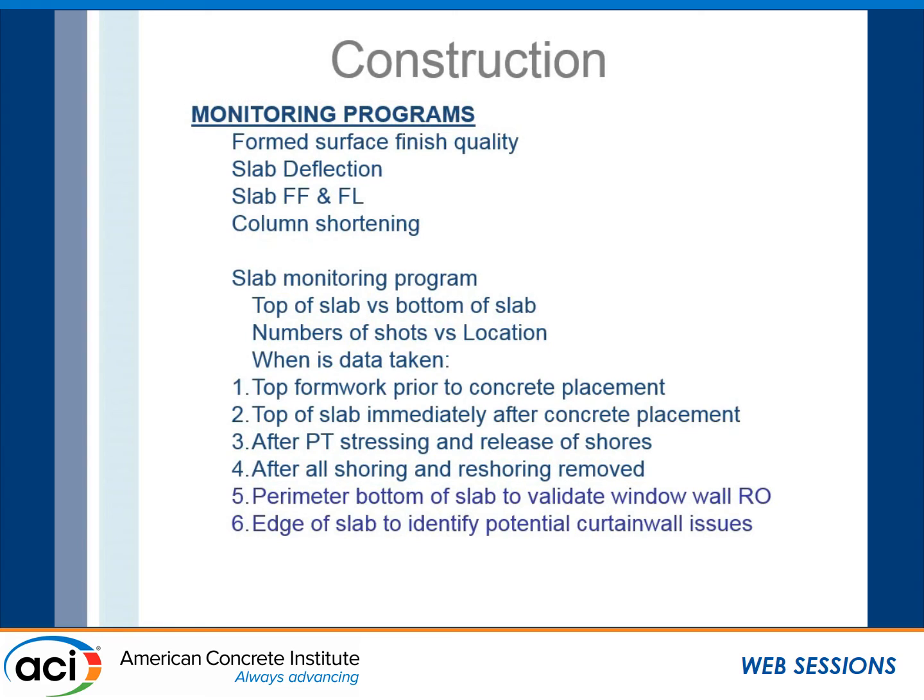Ideally, we would like to go back a second and a third time if the schedule allows, if it's a particularly slab that we're concerned about in terms of performance. But typically, in our market, our interior finishes are close behind us, so we don't typically have the opportunity to take 90-day top of slab elevations.